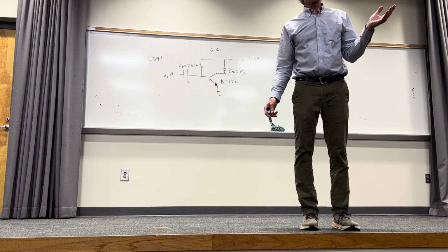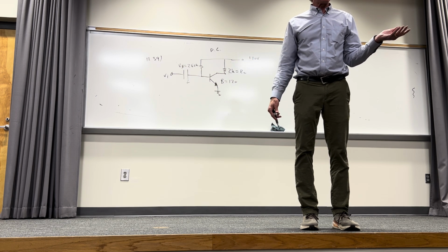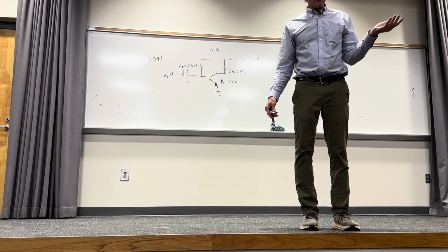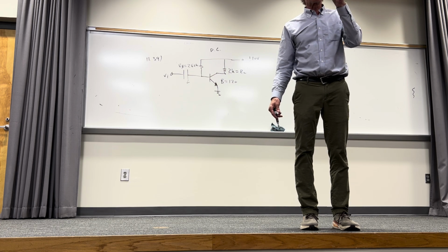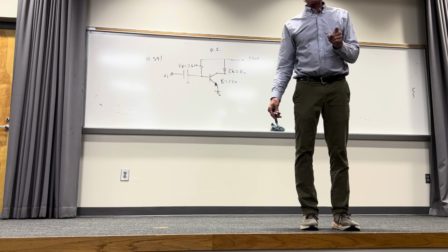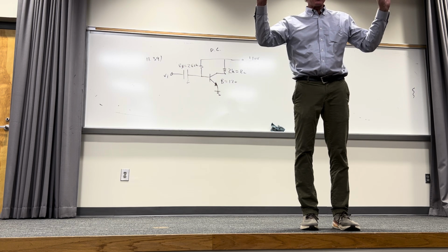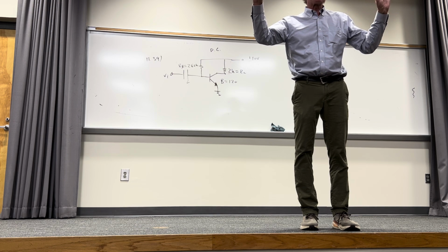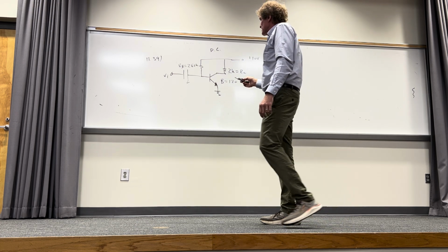A capacitor has a reactance, if you want to think about it in the frequency domain, as 1 over j omega C, right? DC means the frequency is 0, or it's 1 over 0. That's infinity. Infinity is an open circuit. It's two wires dangling, or basically 2 points with nothing between. Y'all follow me on that? So this is an open circuit to DC.